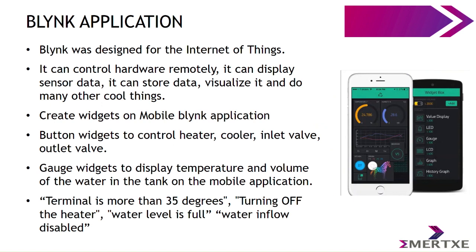The second one is the Blynk application. The Blynk application was designed for the IoT. It can control hardware remotely. It can display sensor data, and it can also store data, visualize it, and do many other cool things. We can create widgets on the mobile Blynk application. Button widgets control the heater, cooler, inlet valve and outlet valve, and the gauge widget is used to display temperature and volume of the water in the tank on the mobile